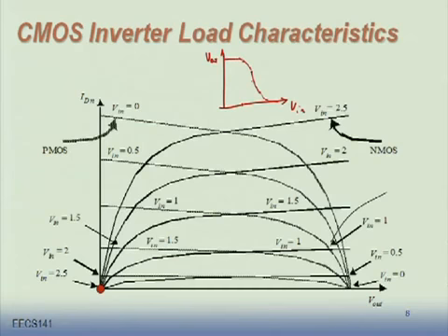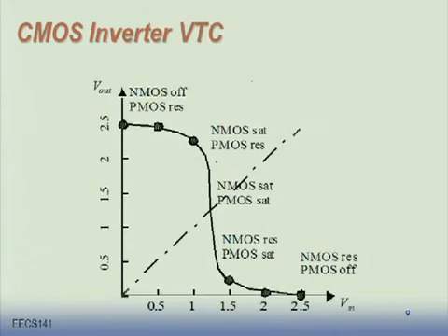It's high VGS. It's ready to conduct. It's just there is no current to conduct. As soon as there is some current, it'll let it go. So although the PMOS transistor also has zero current, we'll call it to be in a resistive region, because as soon as the NMOS transistor starts conducting current, the PMOS transistor will be resistive.